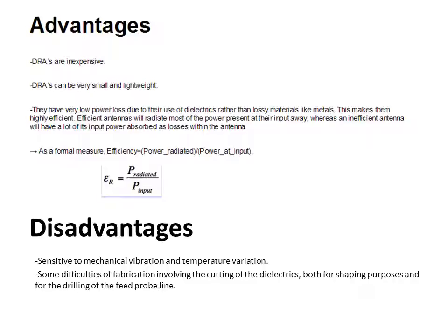Some disadvantages are that DRAs are sensitive to mechanical vibration and temperature variation, and there are some difficulties in the fabrication involved in the cutting of the dielectrics, both for shaping purposes and for the drilling of the feed line probe.